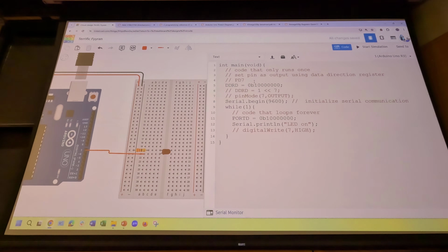In the Arduino IDE, there's a little drop-down menu to select the baud rate. So you have to make sure that what you set in the code matches what's selected in the IDE, or else the data will be all garbled and printed with wrong characters. Don't worry about it too much, just type the 9600.